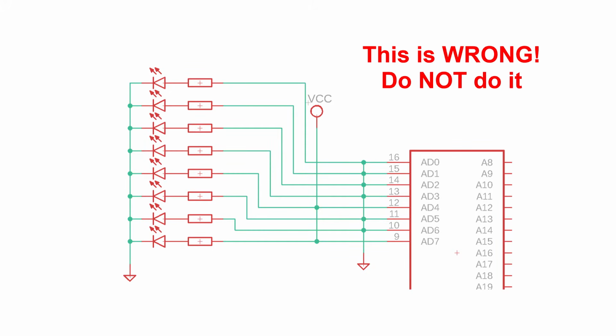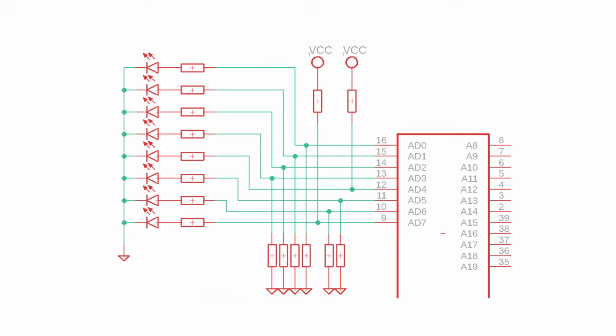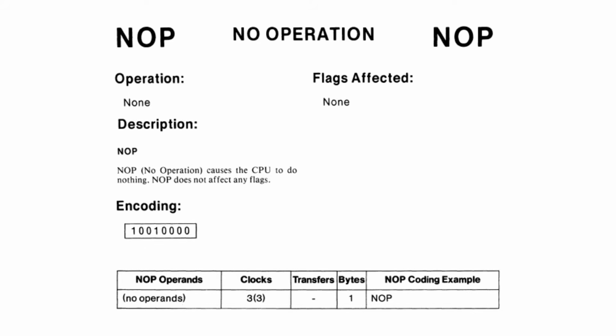We can't, of course, just tie the data lines to either ground or the VCC to simulate ones and zeros, because the lines are multiplexed and are also used as outputs for addressing. What we could do, though, is to use resistors to pull them up or down, but without short-circuiting them. This would simulate the memory, returning the bits every time the processor expects the next program byte on the data lines. I'm going to form the NOP opcode, which is 90 hexadecimal or 10010000 in binary, using 8 resistors between each data line and either ground or the VCC.